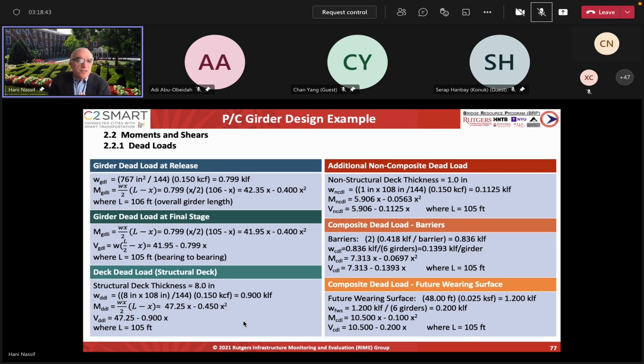The numbers will be different because the moment and shear interact and they're different. The moment is maximum, let's say, at midspan, but the shear is maximum at the support, and there's a variation of the shear and the moment between the two. So for every location, especially at the key points, if you have a tendon draped at 2 points, between the 2 points the maximum moment is the same, but you have to take one section at the drape point and one section outside of it, and then you'll be able to cover most of the impact of the dead load.